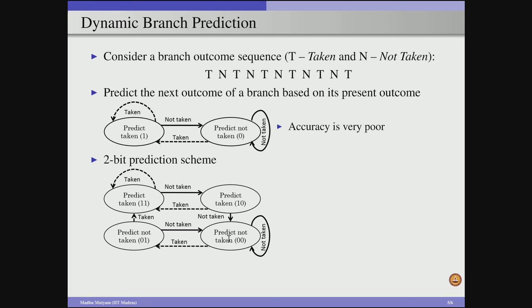And we can actually come up with an n-bit branch predictor, where rather than considering 2 bits, we can have n bits, so that we can get high accuracy. But experimental results show that the 2-bit predictor gives a reasonable accuracy, and the extra hardware overhead we incur because of the n-bit predictor where n is greater than 2 is not good compared to the benefits we get in terms of accuracy. So, as a result we can go with the 2-bit branch predictor in our processor designs.